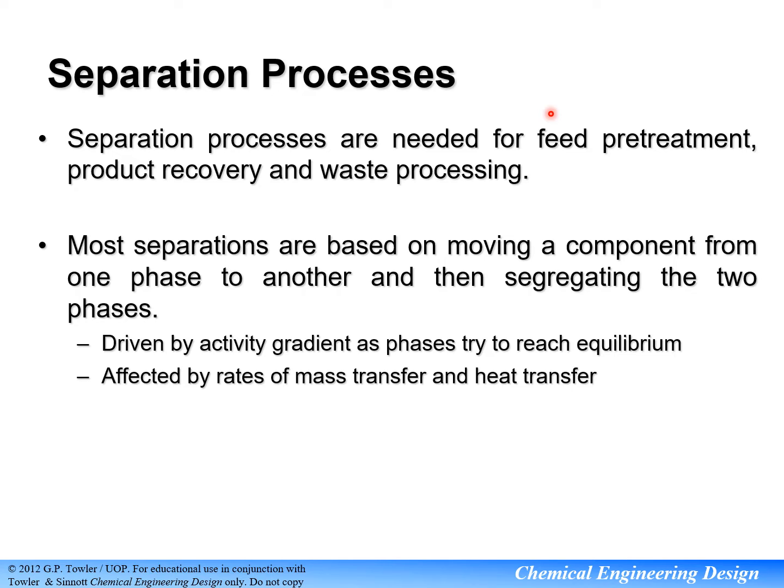Most separation processes are based on moving a component from one phase to another, and then segregating the two phases. This separation process is driven by activity gradient as the phases reach equilibrium. The separation process is also affected by rates of mass transfer and heat transfer.